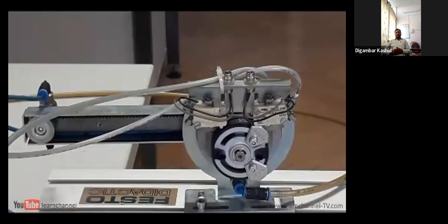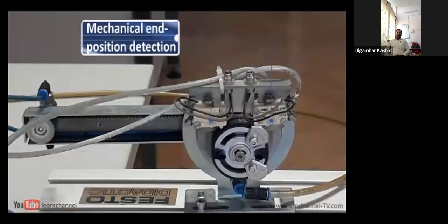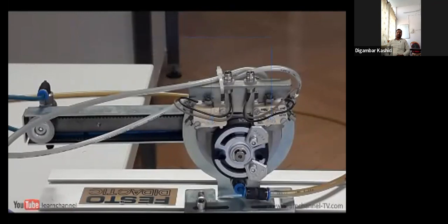Compared to the rack and pinion cylinder, vane actuators are compact in size and less expensive, but the cycle life is limited by the wear of the vane seals. Also, friction caused by the vane seals and leakage over these vanes result in less efficiency.